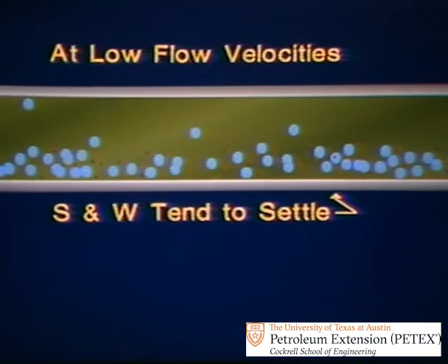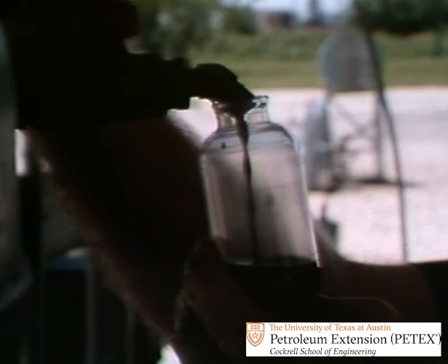Make sure the flow velocity of the oil or product in the main flow stream is adequate, or proper mixing is provided. If it isn't, do not take a sample. And finally, if possible, draw samples directly into the glassware in which the tests will be made. Otherwise, keep sample transfers to a minimum. Don't mess up a good sample by poor handling.